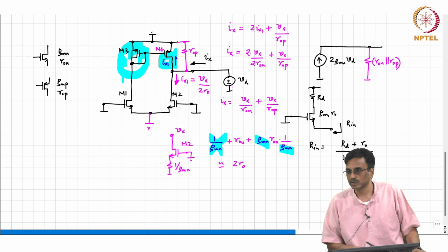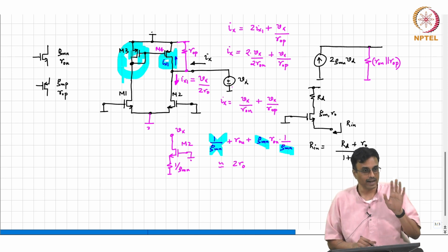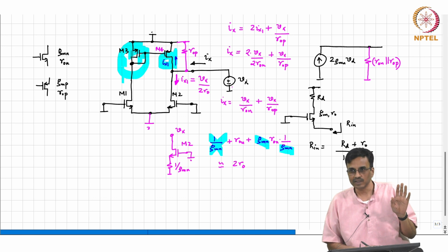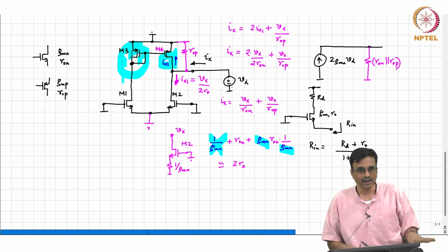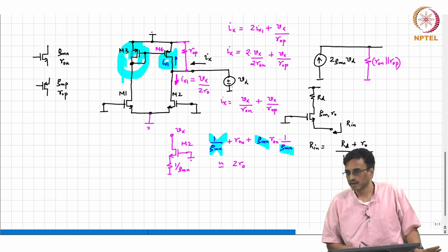And then you will scratch your head and say by symmetry, and then they will say, well, output resistance is not zero, where did you get symmetry? And then you scratch your head and say, I do not know, right? All right, you understand. But this is a great way of remembering the final formula, which is Ron parallel Rop. Okay.